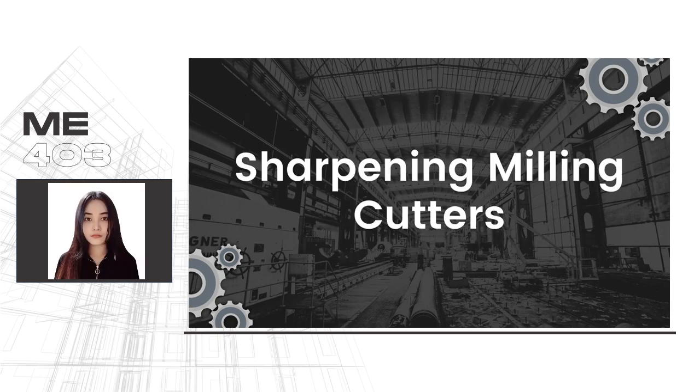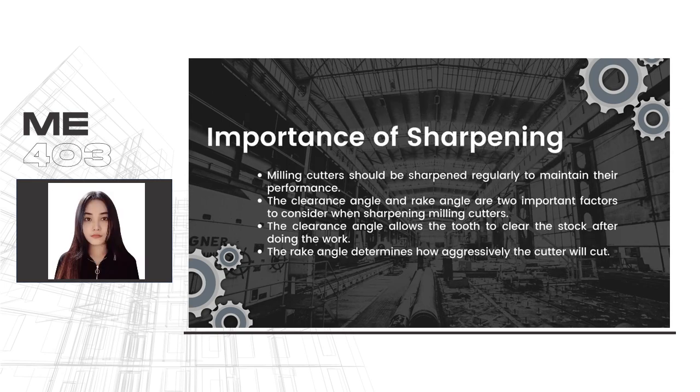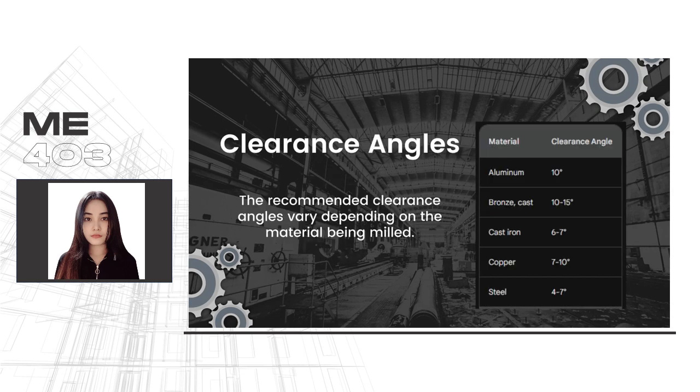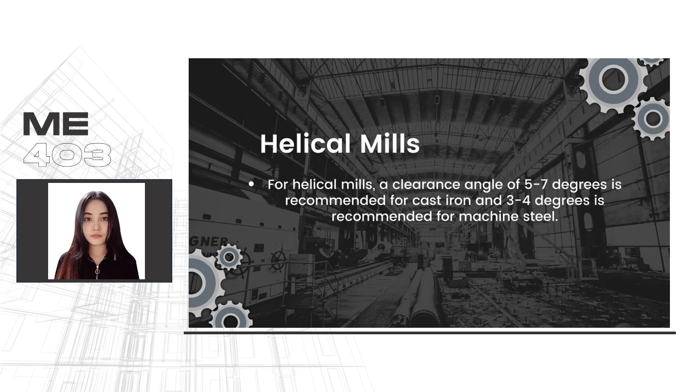Cutters must also be sharpened to attain satisfactory results. A dull cutter does not last long compared to a cutter in proper condition. Angles are taken into consideration as well as clearance angles of the cutters. Presented are the suggested clearance angles of cutters based on the Cincinnati Milacron Company.